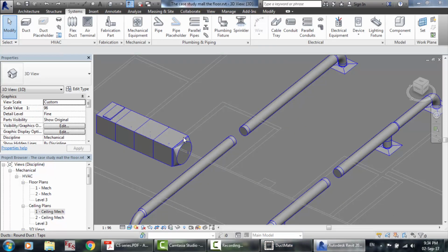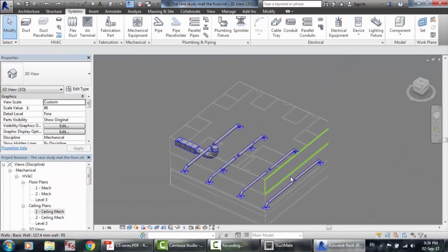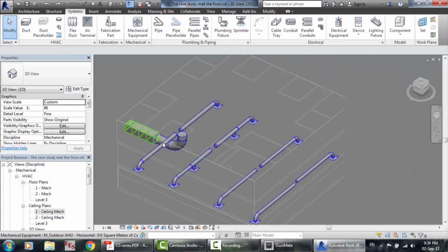So gentlemen, here is a problem. So Control Z to see what happened. Notice that there is a problem here. I think it is because of the distance. So to avoid these kind of problems, you have to make sure that there is enough distance for the elbows. Okay, and this is a very serious problem. So what we have to do is